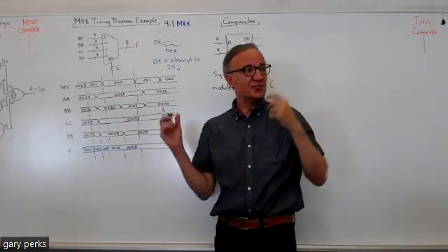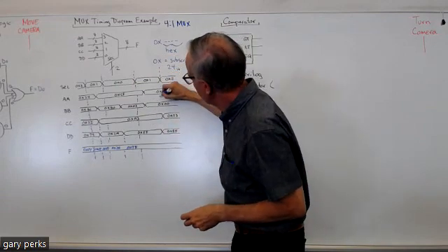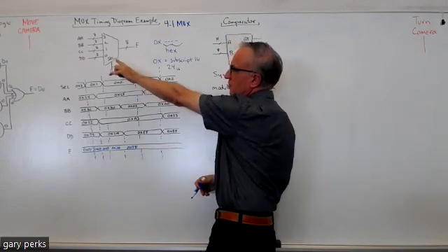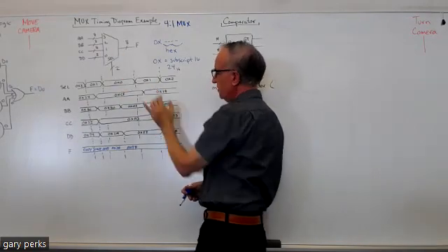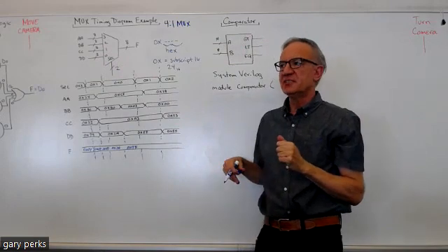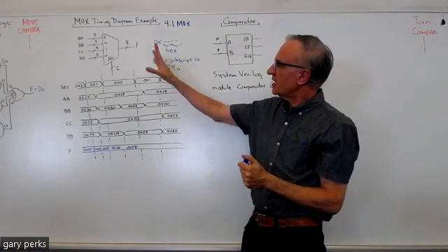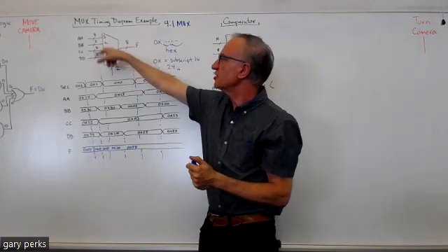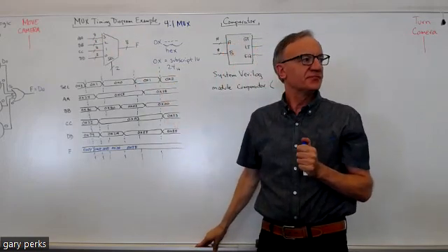All right, so you get the idea. Could you finish this? You can see it just changes to a 1 again. So during this time, it's going to equal CC, right? It's going to equal this data, and then it goes to a 2. So during this last time here, it'll equal the data on B. Do you see how, again, it's acting like a multi-position switch? The select input determines which one of these multiple inputs gets connected to the output.